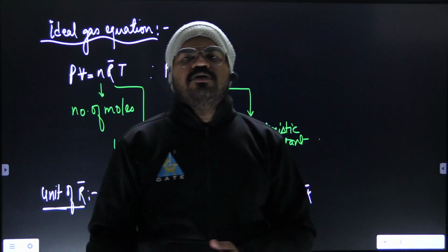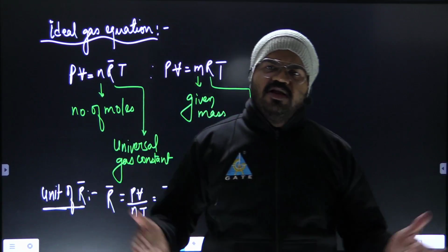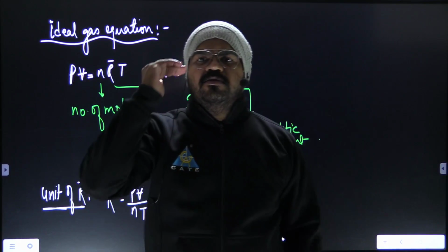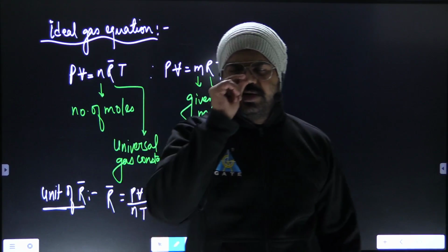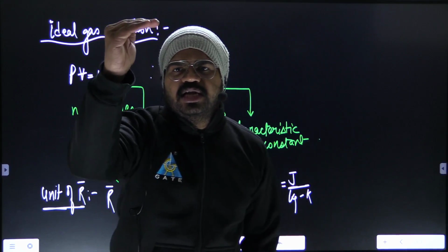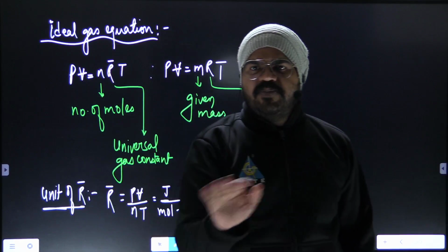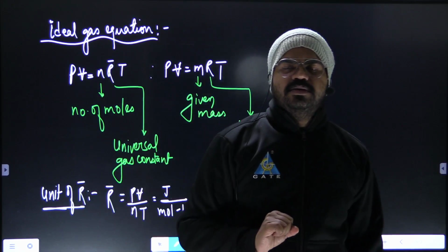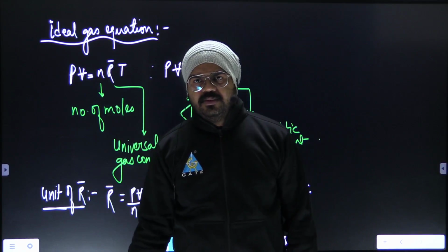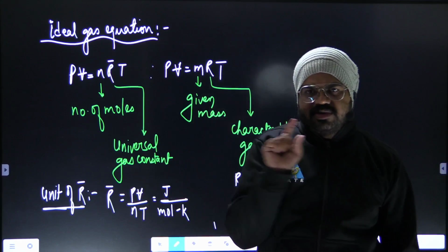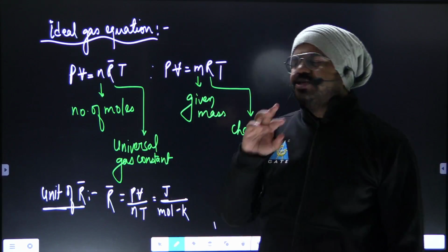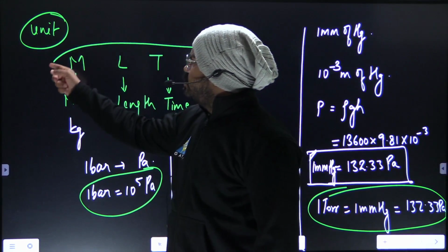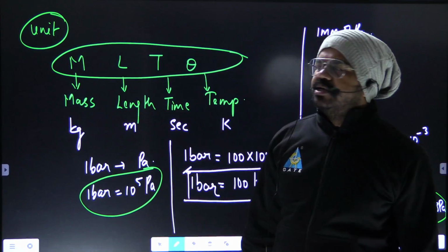Specific fuel consumption is always expressed as mass flow rate upon power developed. Mass flow rate in kilogram per hour and power in kilowatt. So it becomes kilogram upon kilowatt hour. That's how we proceed. So some things you need to remember and some conversions you need to play with. And these are the basic factors you need to keep in mind.